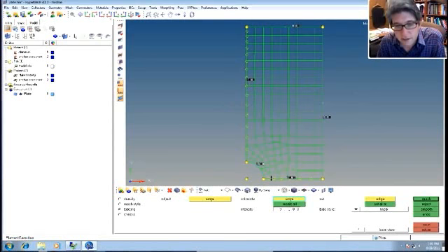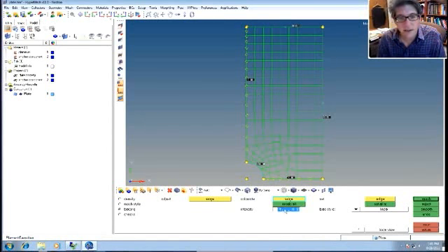And you can see what it does is the bias packs the elements towards a point. So this looks good. I got that packed more to this. And the more I change this bias number, the more it packs them to it. Now this one is packing it to the wrong side, so I think I make it -4 or 1/4. I don't know which one it is. Yeah, if you make it a negative number, it packs it to the other side. So that's kind of nice.